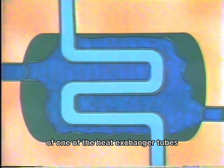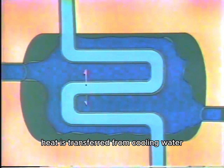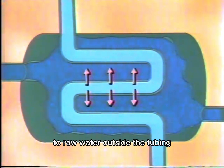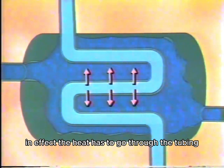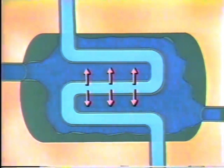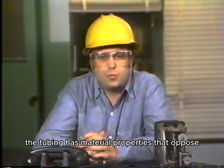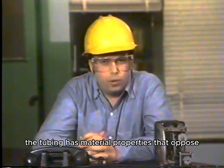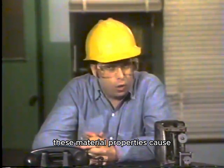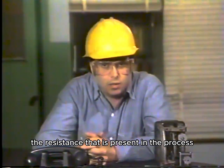Here's an illustration of one of the heat exchanger tubes. Heat is transferred from cooling water inside the tubing to raw water outside the tubing. In effect, the heat has to go through the tubing. The tubing has material properties that oppose or resist the transfer of heat. These material properties cause the resistance that is present in the process.